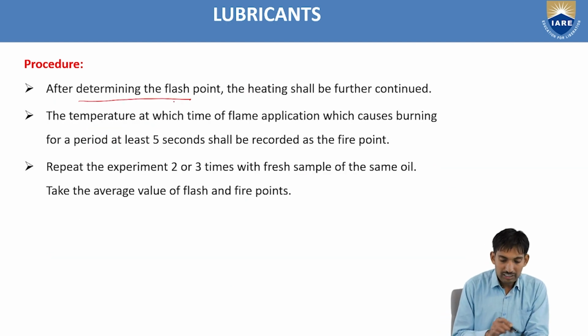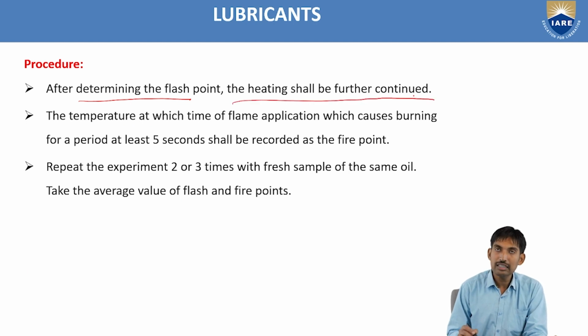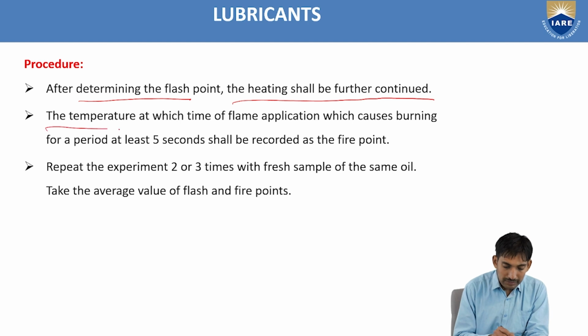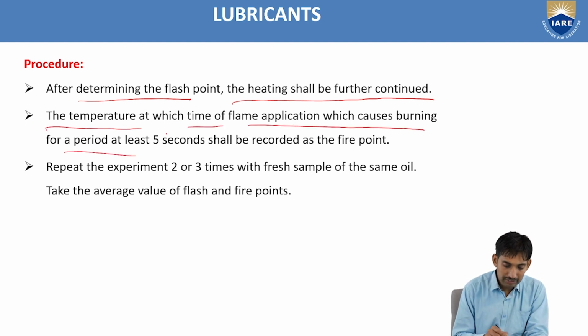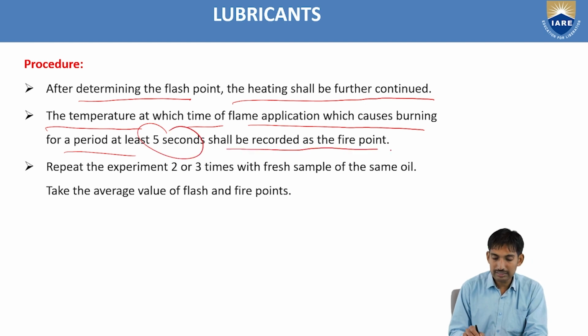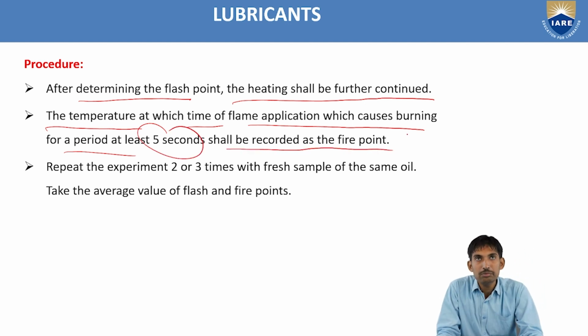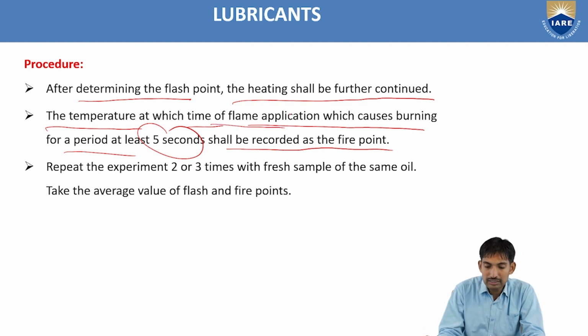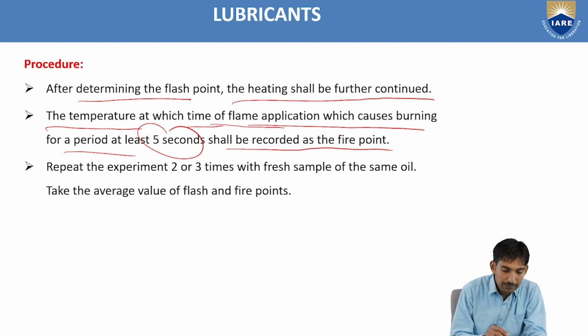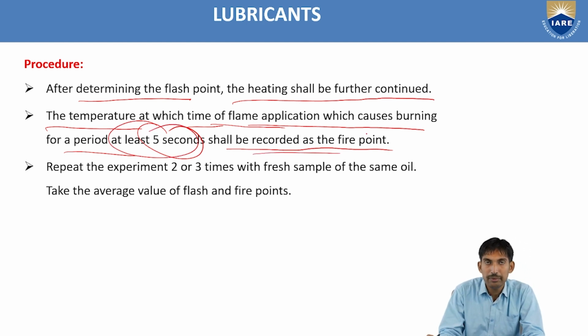After the determination of the flash point, the heating shall be further continued. The temperature at which the flame application causes burning for a period of at least 5 seconds shall be recorded as the fire point. That is called the fire point.